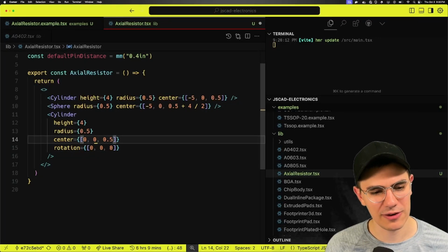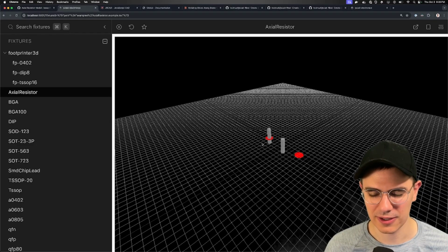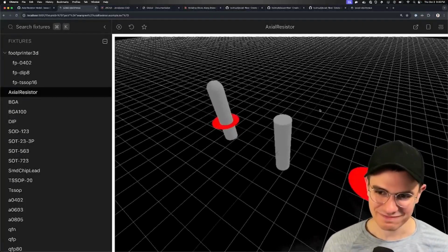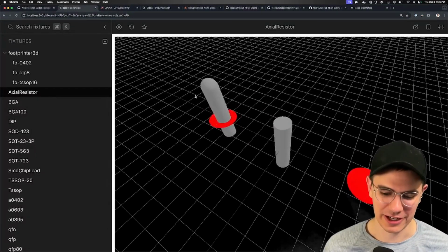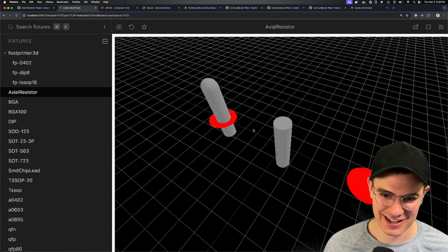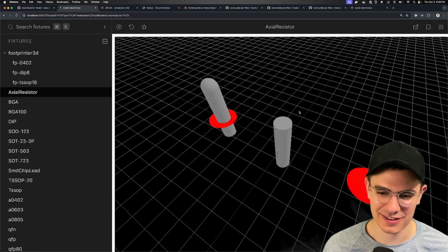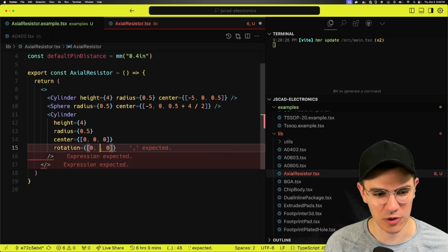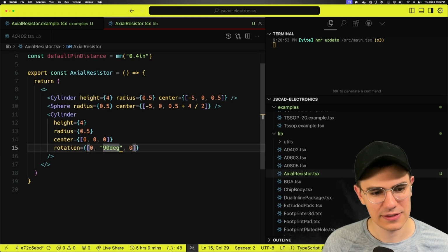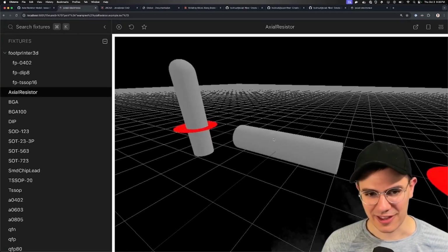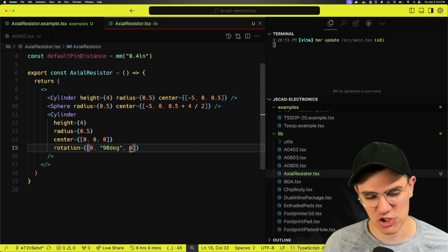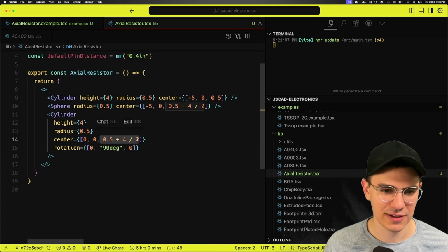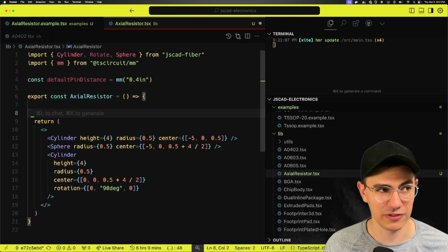For now, we can almost think of this thing as being centered, right? And then let's rotate it. Now, when you're thinking about axes to rotate over, it's really hard to remember what the axes are, but just from watching how this design has gone, this is the x-axis and this is the y-axis. So if we want to rotate around the y-axis, we just set rotation, the center one, XYZ, the center Y to 90 degrees. And you can just mess around with that. If it doesn't work the first time, just change where it is. You'll figure it out.